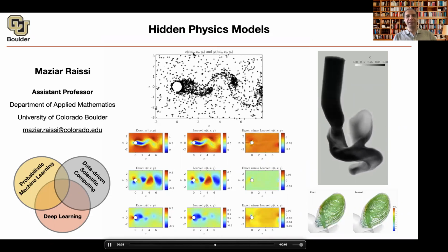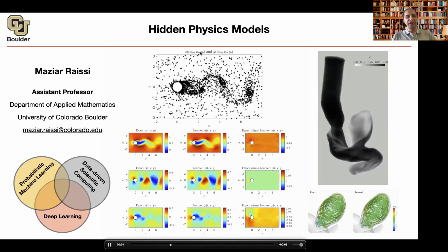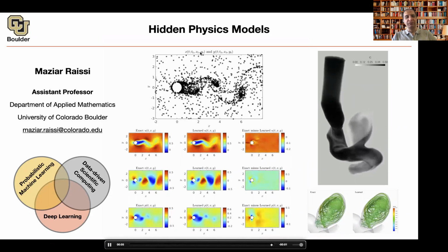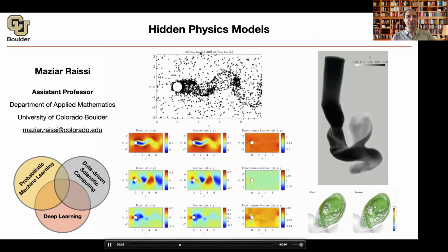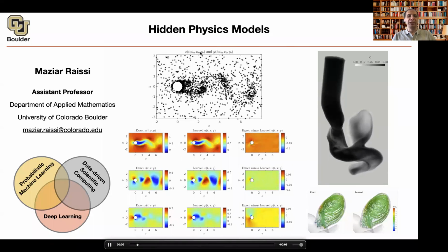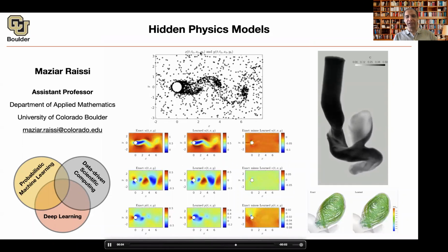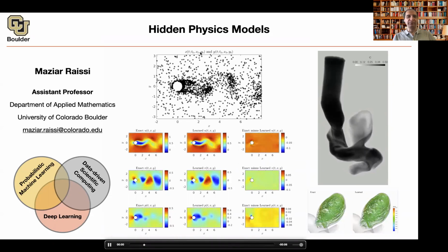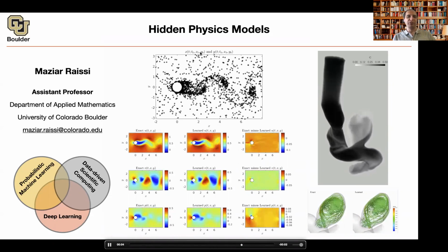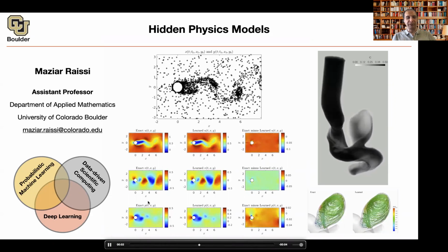And you can have, for instance, 6 columns: at what time the particle was injected, when it was injected, where was it, its X and Y locations, what time is it now, and what location the particle is at currently. That's your data. And from that data, assuming that the Navier-Stokes equations are correct, you want to back calculate the velocity and the pressure fields.